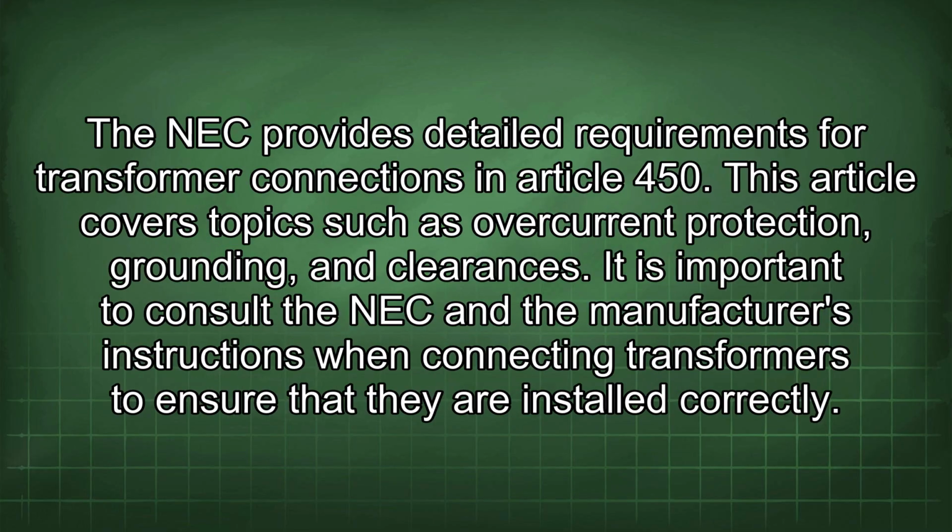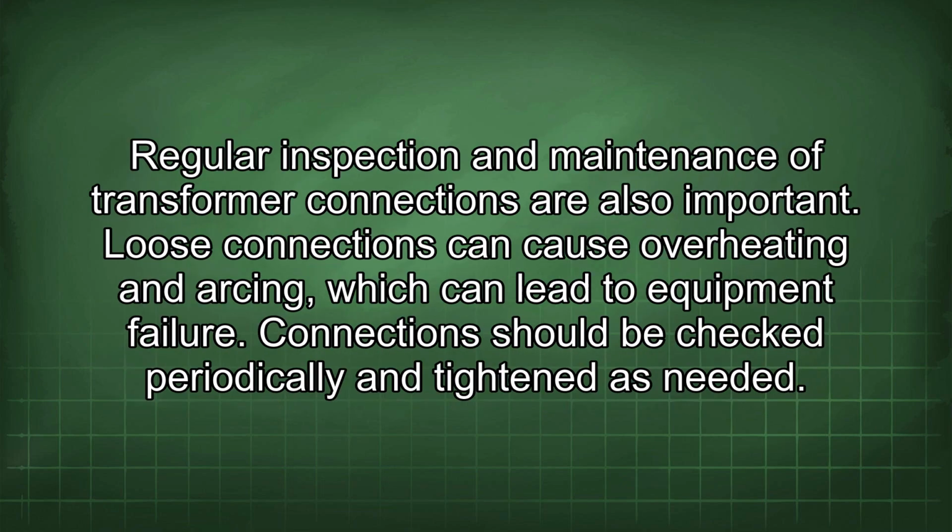The NEC provides detailed requirements for transformer connections in Article 450. This article covers topics such as overcurrent protection, grounding, and clearances. It is important to consult the NEC and the manufacturer's instructions when connecting transformers to ensure that they are installed correctly. Regular inspection and maintenance of transformer connections are also important.